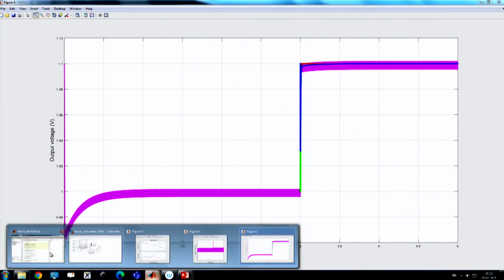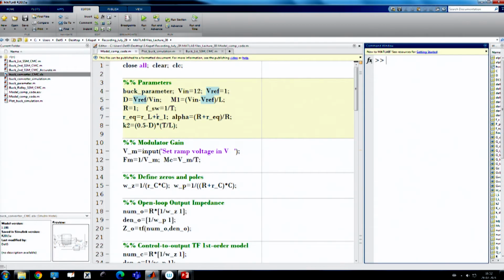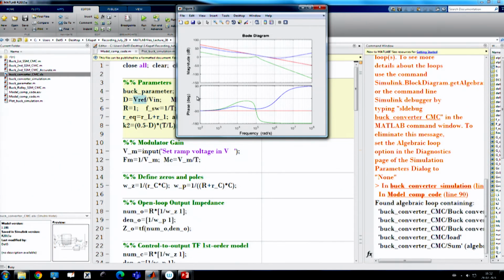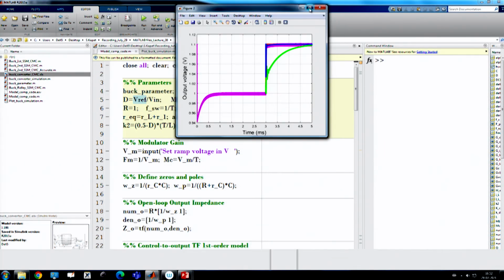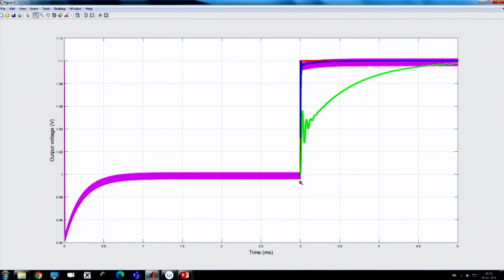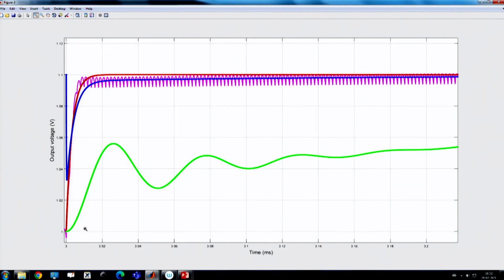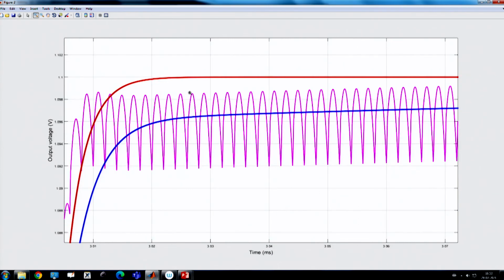Now, we want to see what happens if we add a large ramp. So, we now consider that we have used an overcompensated ramp of 10 volt. I am giving the ramp when it is not required, but I want to check whether the model is valid or not, and 50 kilohertz is the bandwidth I am setting. Now, I am trying to match. You see that the Ridley model is matching fine, okay, and the first order model is matching fine with slight mismatch,